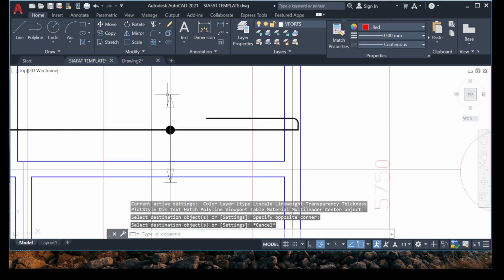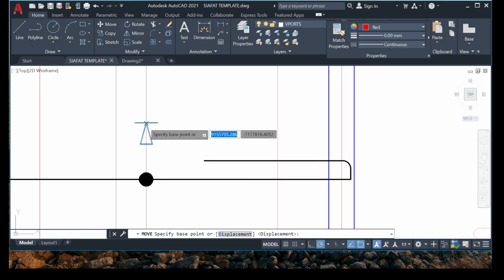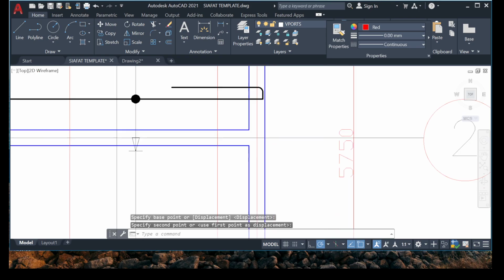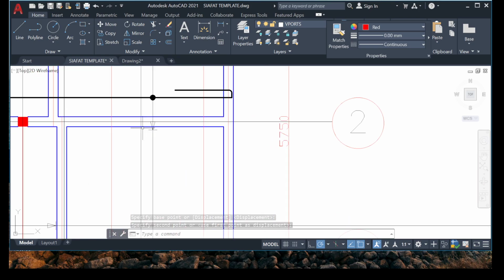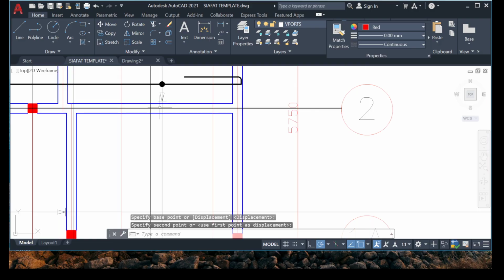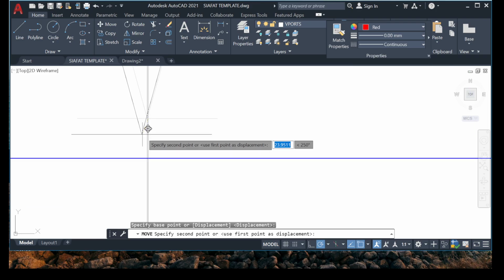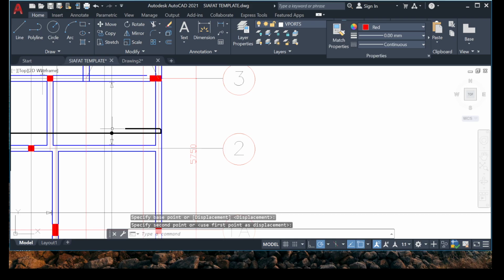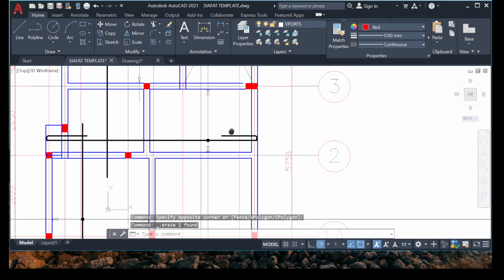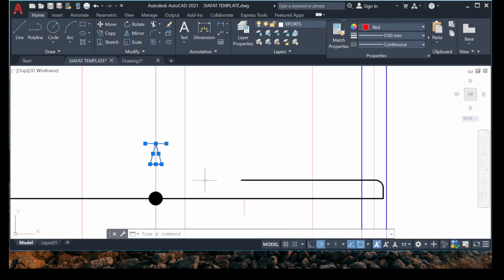Yeah, very good. So let's move this to where it's actually starting from and to where it's ending. So we're almost done with the bottom reinforcement. Okay, this stops here. Let's move this here. Let's let this come down a little bit. Now remember that while doing it, make sure that your cover is not more than 25 mm. Okay, very good. Now let's take this up.